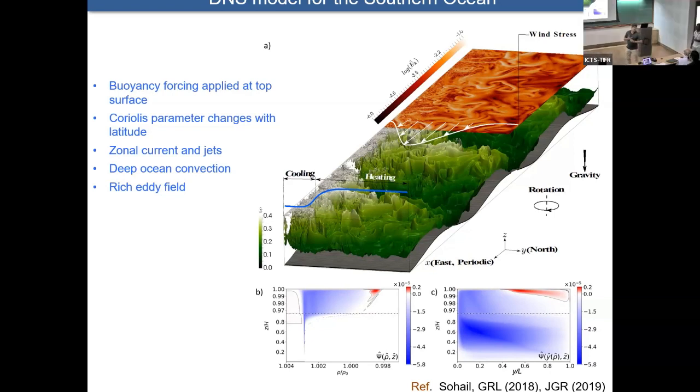Oh, what is the boundary condition on ice? We put 3 boundary conditions, or not 3, it's 4 boundary conditions in the ice. First, we'll talk about the velocity boundary. Velocity, you can put slip condition and no slip condition, right? Depending on how rough you want to make the ice. So if the ice is very rough, you can put some roughness boundary condition for the momentum equations, right? Of course, no penetration condition. Nothing is penetrated in the ice also.